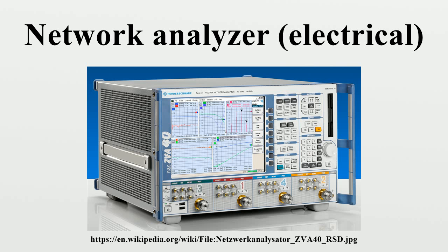There are several different methods of calibration. SOLT, which is an acronym for short, open, load, through, is the simplest method. As the name suggests, this requires access to known standards with a short circuit, open circuit, a precision load and a through connection. It is best if the test ports have the same type of connector, but of a different sex. So the through just requires the test ports are connected together. SOLT is suitable for coaxial measurements, where it is possible to obtain the short, open, load and through.